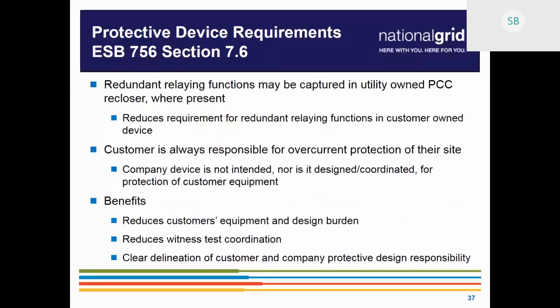All right, so protective device requirements. Up till recently, in the past, we have required the redundant relaying to be on the customer side. We have transitioned over to the approach of allowing those redundant elements to be within our PCC recloser. So the primary elements are the ones that are within the inverter. The secondary ones, the redundant ones, were previously required to be in a utility grade relay that the customer owned. We are now putting that into our PCC recloser